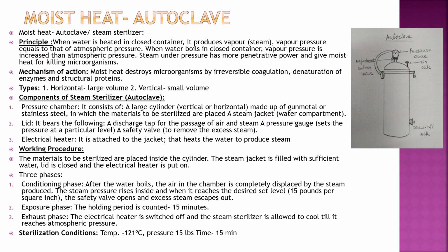Now there are three phases. First is the conditioning phase, second is the exposure phase, and third is the exhaust phase. In the conditioning phase, you have to set the conditions of temperature, pressure and time. That is temperature 121 °C, pressure 15 lbs and time 15 minutes.